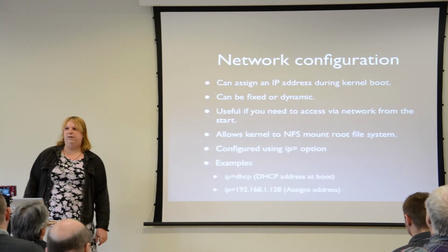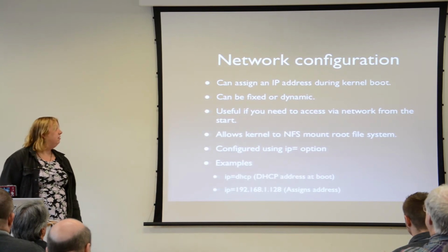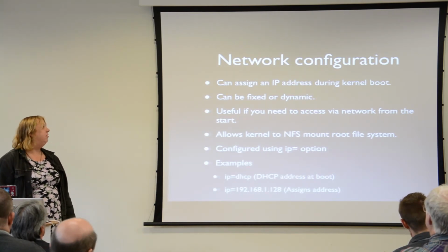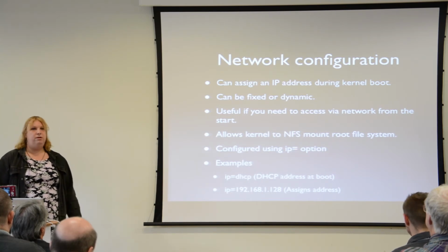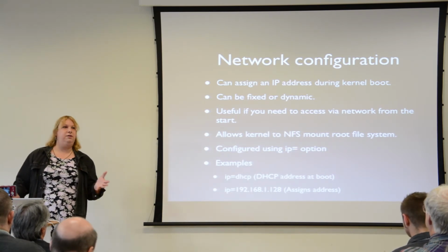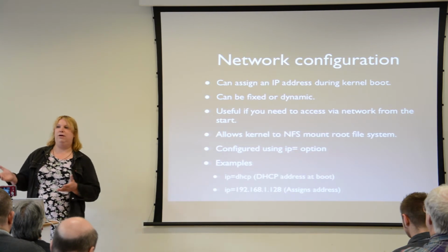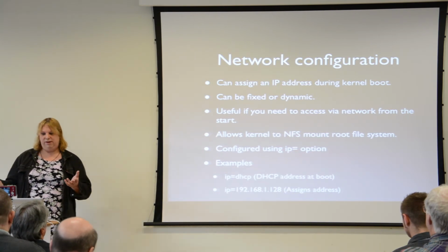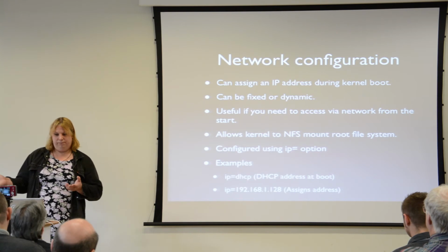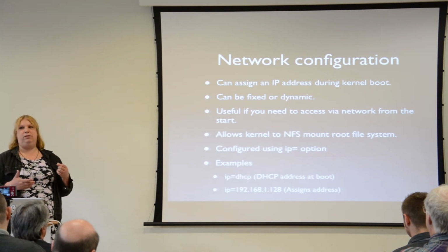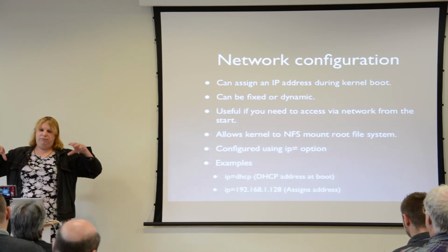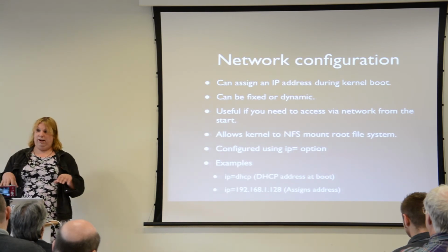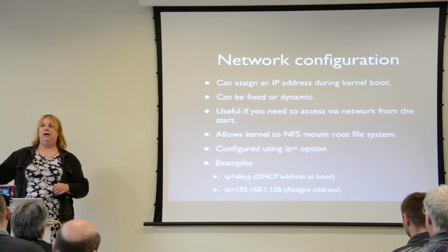You can actually configure the network during boot, which is kind of useful. You use the IP option. Why do you want to do this? The kernel can actually mount a file system that's on another machine via NFS. In our development at work, we do a lot of stuff where we build everything and keep the root file systems on our development machines. And all our device has on it is the bootloader.